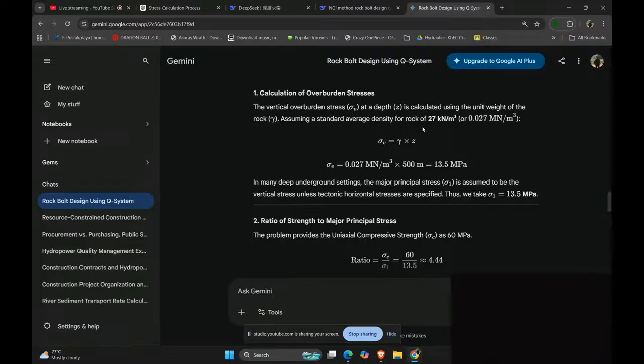Your equivalent dimension is 6.25 and Q is 4.64, which places the tunnel excavation in category 4, which requires a pattern of rock bolts at spacing of 2.3 meter and 40 to 50 mm of unreinforced shotcrete. Class 4 means 6.25 to 4.64, so it lies in class 4, which requires rock bolt spacing of 2.3 meter and 40 to 50 mm of unreinforced shotcrete.